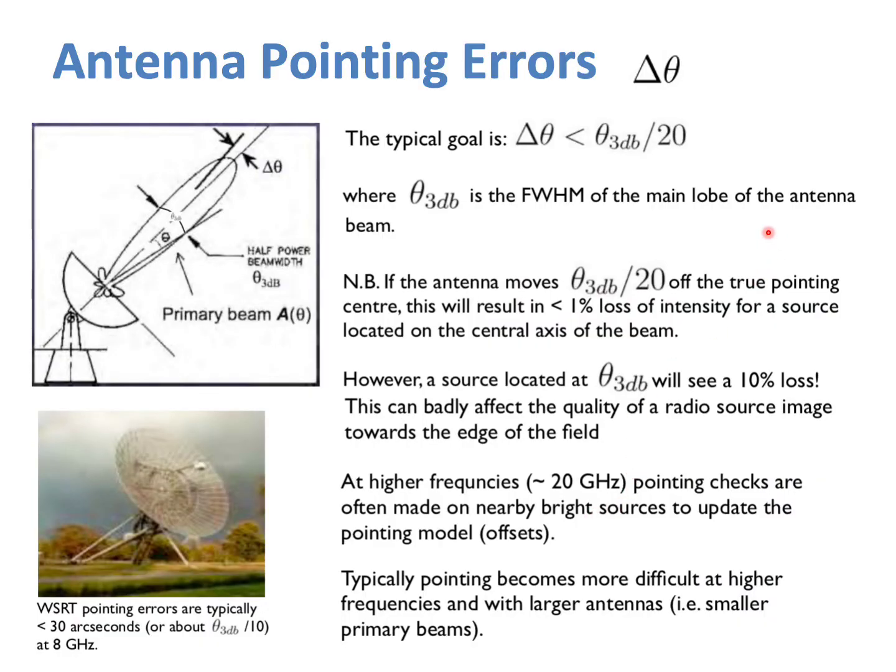Okay, so we know about aperture efficiency and total efficiency and pointing efficiency, or surface accuracy, but what about pointing errors? We'd like to point at what we think we're pointing at, but that's not always the case. There's often some pointing error. That pointing error we want to be below 1/20th of the full width half max of the main beam.